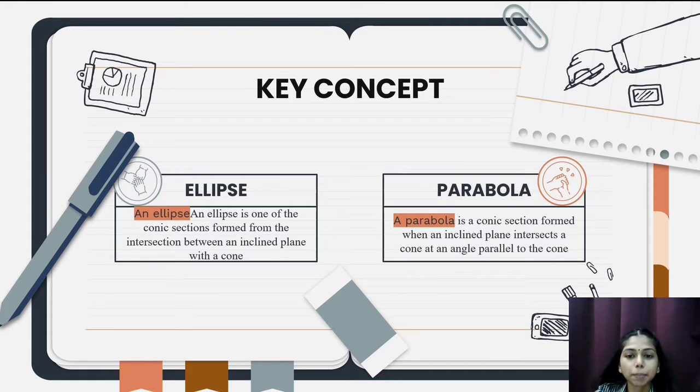When the structure is being built and the main cables are attached to the towers, the curve is the catenary. The cable of a suspension bridge is under tension from holding up the bridge. Therefore, the cables of a suspension bridge form a parabola, because the weight of the deck is equally distributed along the curve. Parabolas are used in suspension bridges because the bridge deck or roadway is supported from above, using tension in the cables and compression in the towers rather than just from the bases.